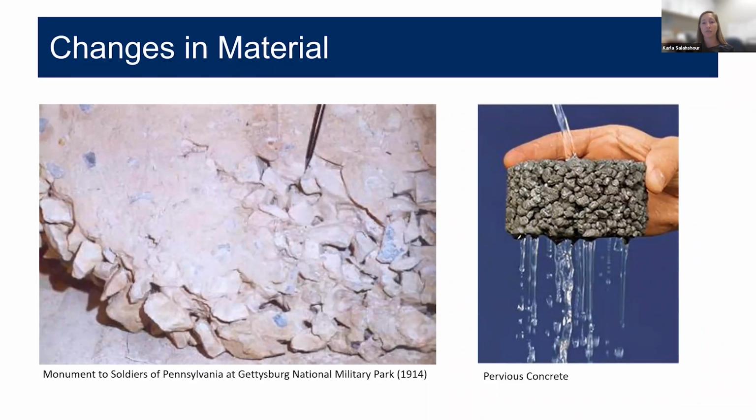And that increase in water content allowed us to place the material. And so our concretes had a lot of bleeding, for example. And this is one reason why dry shakes worked so well in the past in industrial settings. But in modern times, we've found that labor is much more expensive. So mixes would increase the cement content because the cement was actually cheaper than the labor.